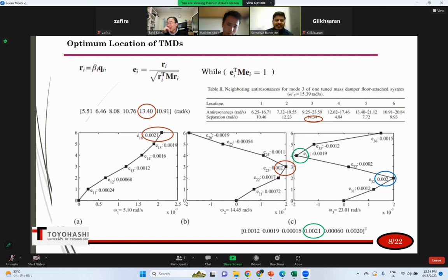Yes, sir. I mean, in the frequency response function curve between two resonance conditions, there is one peak on the negative side where the response is very small. I think that is referred to as the anti-resonance frequency by some researchers, and I think that region is more suitable for the structure because the response is very small.